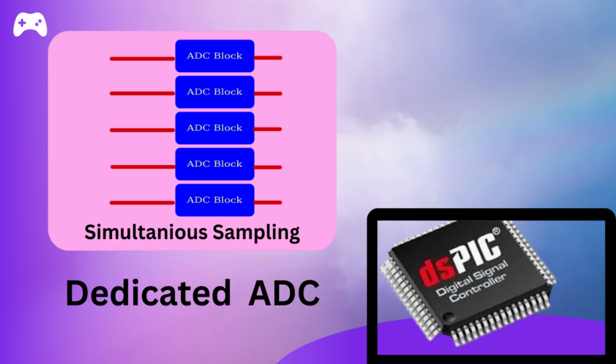So these are dedicated ADCs. The number of ADC blocks depends upon the device number. All these ADC blocks can simultaneously sample the input analog signal and convert them into digital format. So both the features, shared ADC and dedicated ADC, are available.